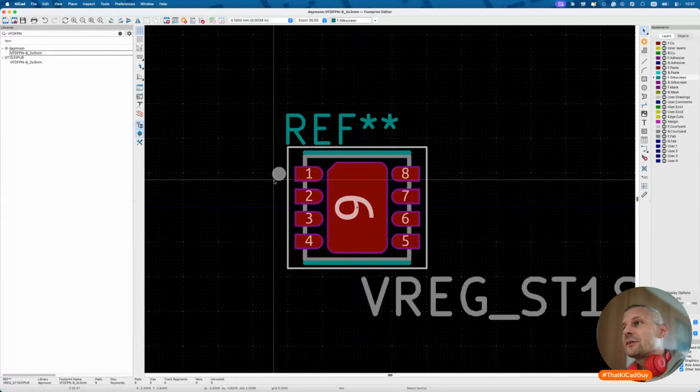The dot near the pin 1 is great, but not in the footprint. Why? Because I don't know why. Anywhere it is, it always interferes with some vias. So I don't put it into footprints, but in the post process, in the cosmetic job of the PCB, I add all pin 1 marks.